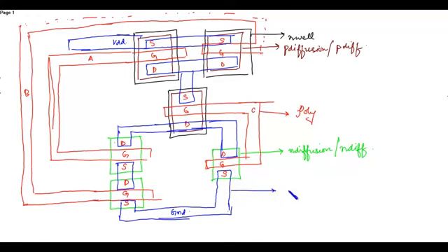So this is your metal one. Now after connecting all this is your output. This is your output because output is obtained at the drain terminal. Now place the contacts. First the diffusion contact, that is connecting the metal with the P diffusion layer.